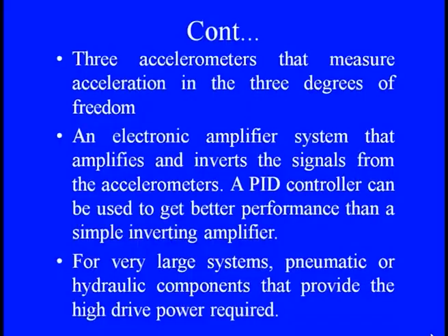And when we are talking about the sensor or actuator, which is an integral part of the active vibration control, without which we cannot even think to gauge the amount of forces and to counterbalance them, the accelerometer is one of the important components in this. And the accelerometers, either single axial, meaning uniaxial, to triaxial accelerometers, are effectively being used as the sensor, and then whatever actuation is required, the force is actuated through these actuators.